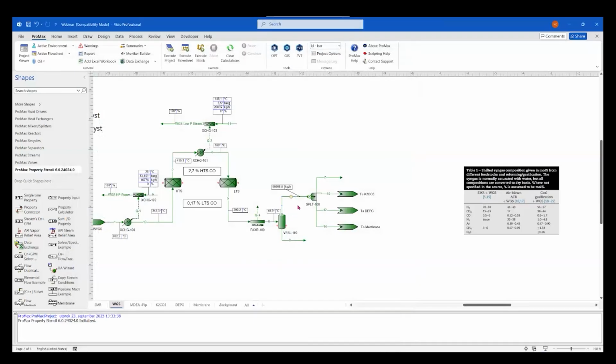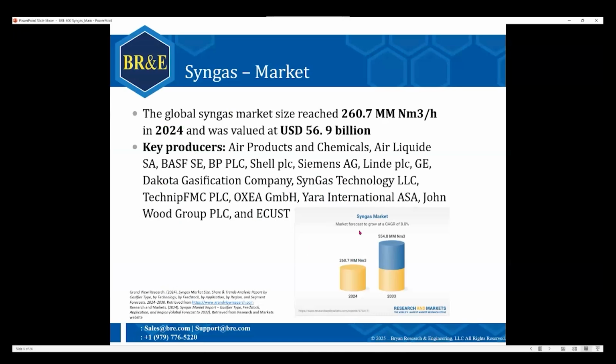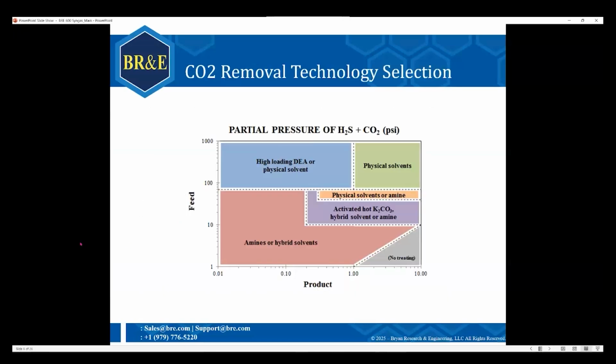This product stream I'm sending into the splitter, and inside the splitter I'm taking this stream times 4, and then I equally split it into these 4 streams. So all these 4 streams plus this stream are equal, and every stream I will be sending to a different type of carbon capture technology. And again, I will use the cross flow sheet connectors. Now I will go back to the presentation.